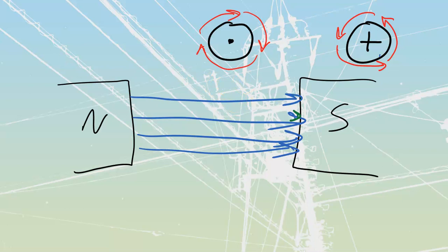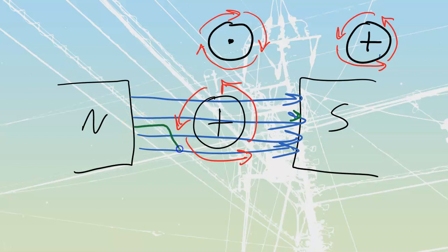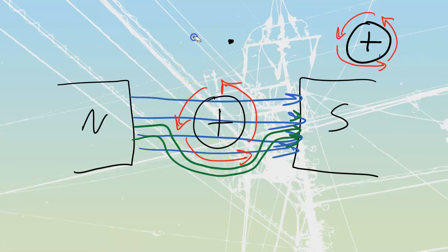If we were to place the other current carrying conductor inside of here, so now it's going to be the one with the current traveling away from us that has got its lines of flux traveling around and around and around like that, what we would see is, once again, my lines of flux are going to leave from my north pole. As they do, they're going to get caught and torn around, and then they're going to leave and go back to that south pole over there. Any of my lines of flux are going to do this, which once again means that I have got a rubber band, an elastic, a slingshot over here that is being pulled down, and the direction that it's going to want to repel this conductor is going to be just straight up.